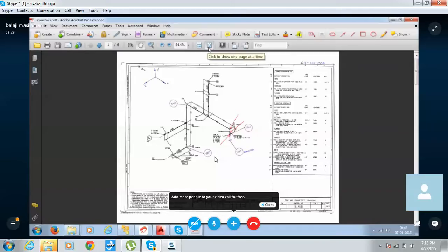Generally, we'll give design and operating. If you want to know what will be really acting on the expansion, then we can give the minimum design metal temperature. Because that's standard one, right? No, not standard one. It will be given in the line list itself. If they have not provided, no need to give that one. In our projects, they have provided that minimum design metal temperature.